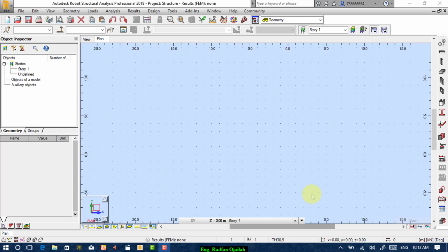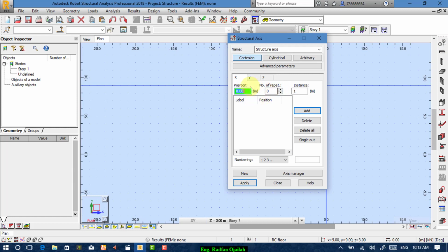So what should we do to start making cladding? Well, first we do our usual steps of making a new grid. Define for the x-axis, for example, 2 and 5 meters, and for the y-axis we have 5 meters values, no letters, and for z we have 4 meters, and values do not include stories.